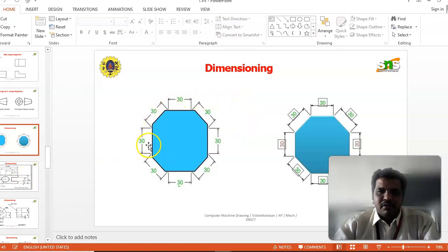We can give the dimension representation by using an arrowhead. The arrowhead is a closed arrowhead with shading. An unclosed arrowhead without shading is a bad representation, and also an incorrect method. So we just want to follow this method.